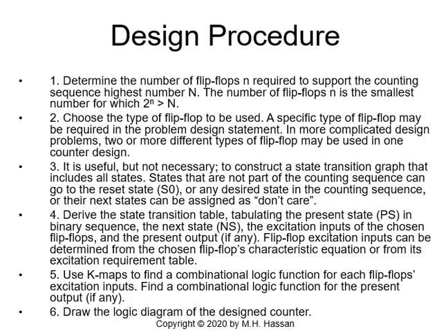Step 2. I will choose the type of flip-flop to be used. A specific type of flip-flop may be required in the problem design statement. In a more complicated design problem, 2 or more different types of flip-flop may be used in one counter design. So here we could use a D-type flip-flop, or a T-type flip-flop, or SR flip-flop, or JK flip-flop. Now, the type of flip-flop depends on the availability and the cost of the flip-flop. You know, SR flip-flop is the cheapest, or SR latches. So often they are chosen because of the price.